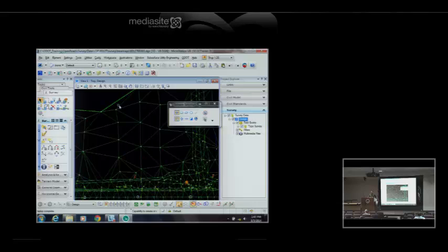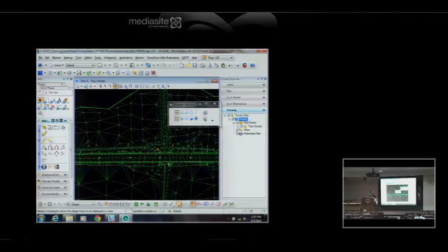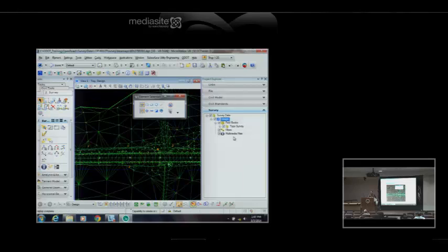Okay, the data itself, since it's in the file, if I want to see this stuff, over here in Project Explorer, my survey tree, if I look at that field book, topo survey, and expand that, so there's the data file I imported. Under that data file, I have different things. So there's the point features. So here's all the point features that are in that data file. And that's the same old ODOT code list that's been out there for years, read from the SMD file.